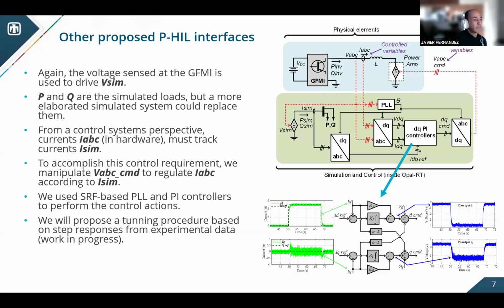data. We also tried some frequency sweeps to try to characterize with Bode plots, but you can see that since those types of tests should be in small signal, this type of noise, as you see here, obscures some of the dynamics. But I think we're still in good shape to do some step responses and try to come up with a procedure to properly tune or optimize the tuning of these controllers.